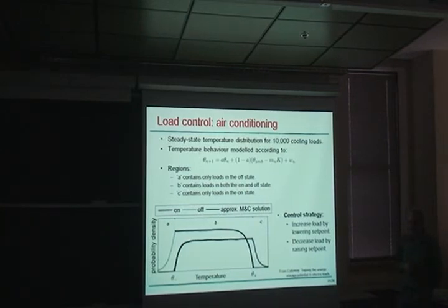But in that case, if you look at it from the standpoint of summertime air conditioning loads, which are stressing the system in terms of capacity, then by a slower modulation of the load demand, by basically shedding air conditioners, you could reduce the demand on the peak capacity of the system.